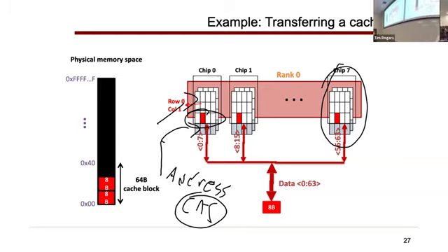Yeah. You said that to get multiple columns in one row, you need to set multiple CAS commands. Yes, correct. Are those pipelined, or how does that work? Well, what do you mean by pipeline? Does it take one cycle to do a CAS, in effect? Yes.